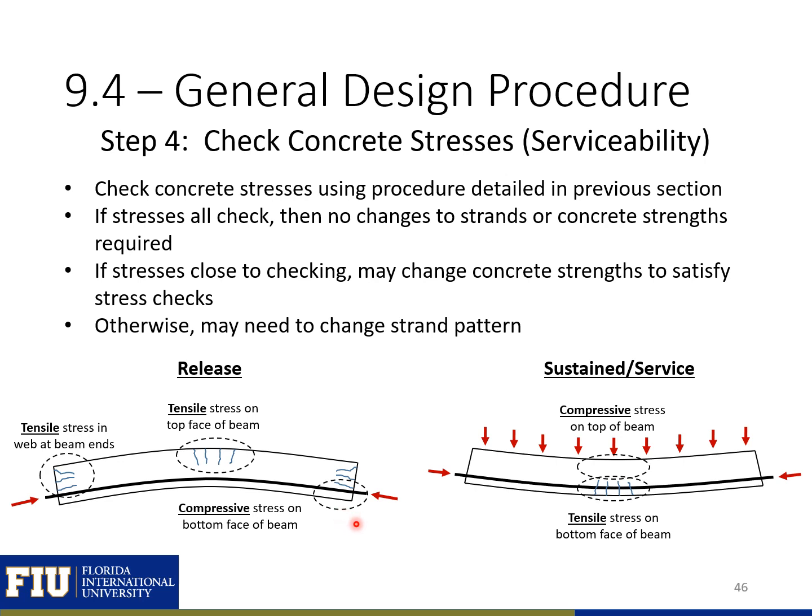At service, typically our tensile stress on the bottom of the beam is going to control, both due to our sustained loads and service loads. Although there is a limit on the sustained compression stress in the section, which may be at the top of the beam at midspan.